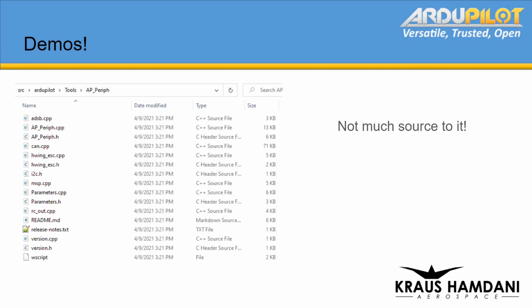There may need to be something special for DMA handling for fast sensor feedback or whatnot, but all that's in place. And you can even spin off your own threads, just like any other library does. In fact, all the libraries do that right now. For example, with the AP_RangeFinder, if it's an I2C bus, all that comes in already, and it spins its own thread off for the I2C bus it's on.